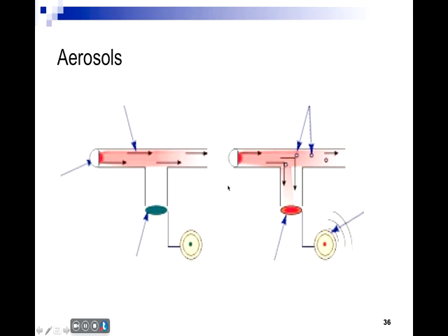Now, alternatively, if you have a dusty environment where there's lots of particulate matter and you shine a light beam from one end of the area to the next, some of that light is going to hit the particulate matter and cause it to scatter. This would be like taking a flashlight and shining it through a dusty room, or driving at night during a snowstorm, where you will see reflections of the light where it's being scattered. And what will happen is that less light is being transmitted from one end of the beam to the second, and some of that light is being scattered over to the plate here. It's red, where you can actually measure it.